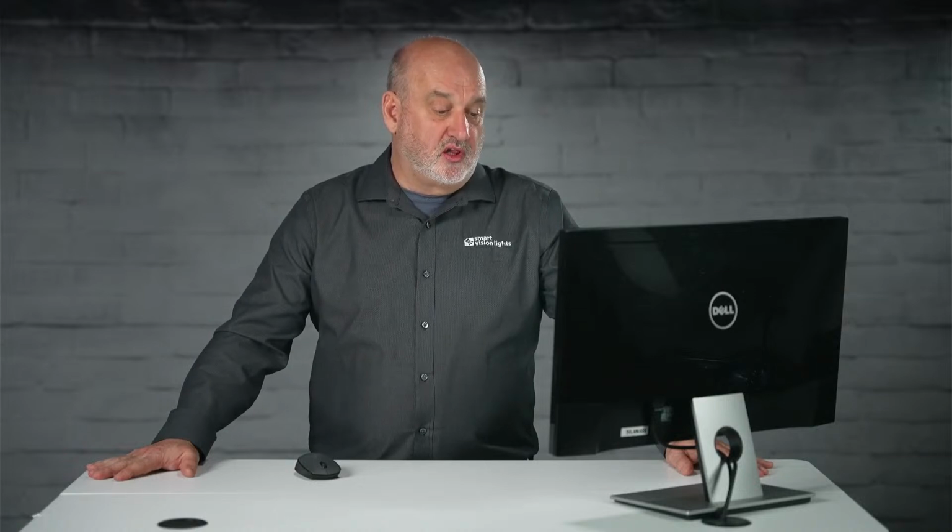The next question says, since the duty cycle is heat related, can I cool the lights to get a longer maximum pulse or a higher duty cycle? Well, that's a good question. We get this periodically. So again, we have to make the general product meet the full specifications, including the temperature range from -10 degrees C to 40 degrees C. And out of that, we set the duty cycle for the light by design and make sure everything is within the envelope for that entire range.